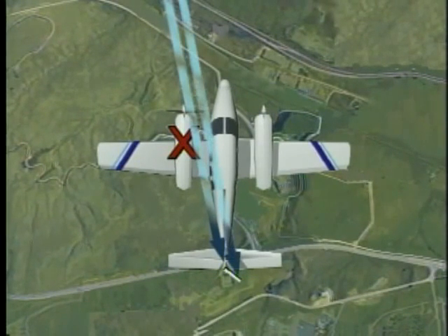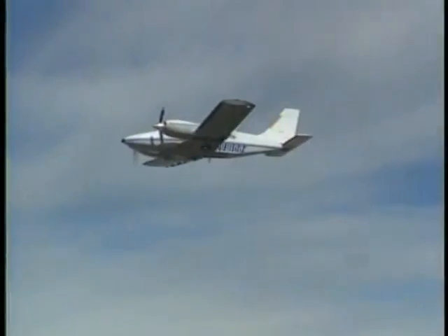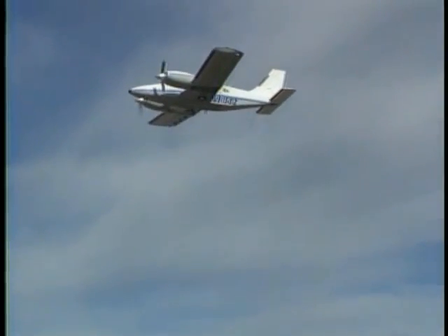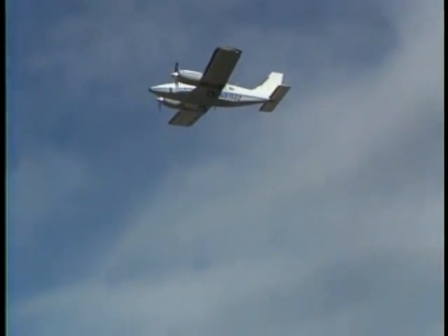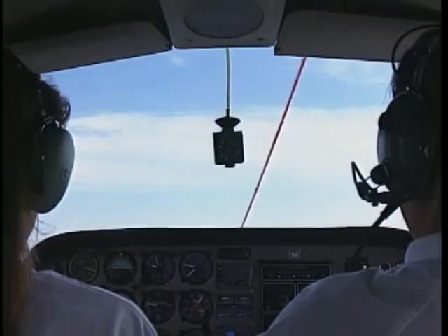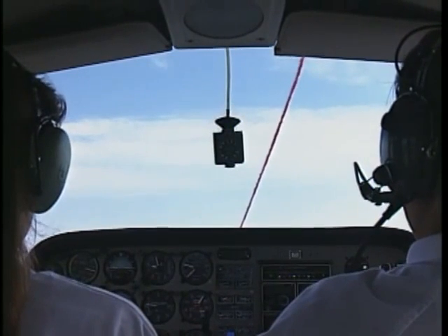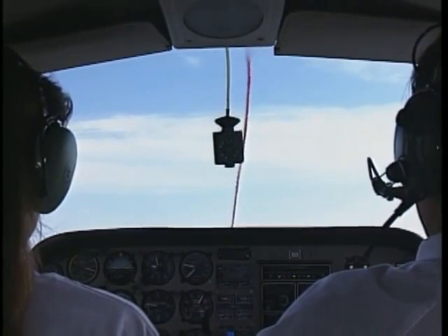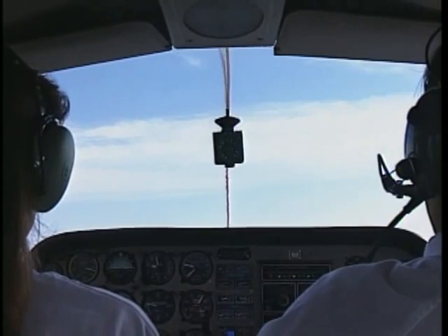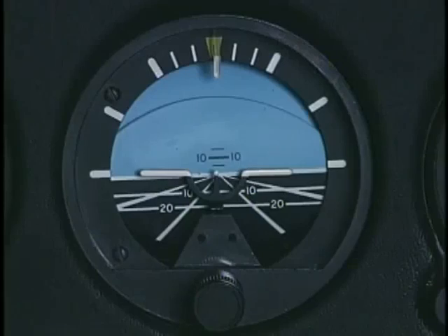And the airflow that does reach the rudder contacts the control surface at a smaller angle. Aside from increasing the actual VMC of the airplane, a side slip also increases drag, which will result in reduced performance. By establishing the precise amount of bank to create a zero side slip condition, the pilot will increase performance and controllability and decrease actual VMC.